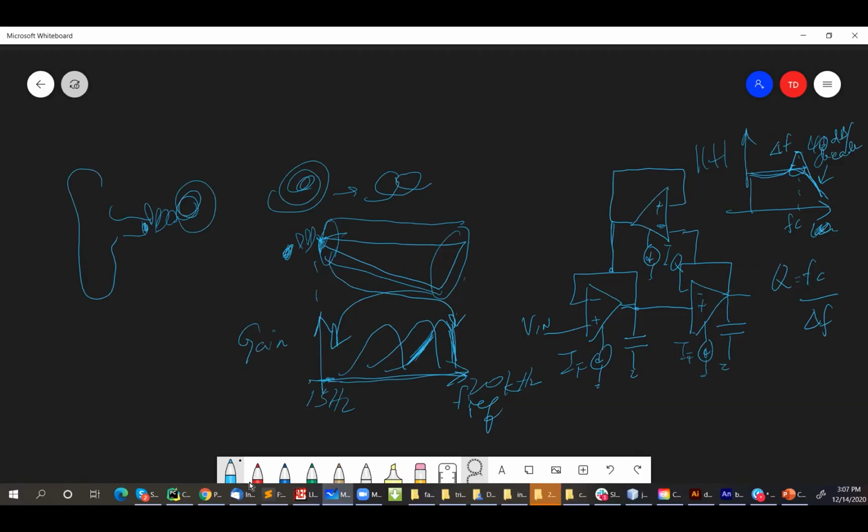And so one easy way to do this is to take the output of the first stage and the output of the second stage, and then you go into yet another amplifier. Okay, so it's like a differentiator. And what that would do is give you kind of a band pass filter look, okay? So it's not as sharp as what you get from the biology, but it's very expensive to create a multi-order filter in silicon. So usually people tend to stay with second order sections or fourth order filters at the most. Okay, all right, so that means that we've got the front end of the cochlear channel.